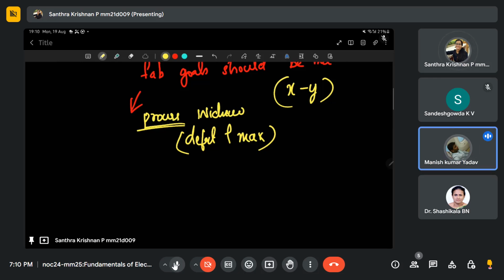And if the thickness is not lying in this x to y range, we will reject the particular wafer. So that is what is done in the process evaluation process. Everywhere, for resistance, conductivity, thickness, etc., we will define a range of values within which the manufactured IC should lie. Anything outside that will be rejected.